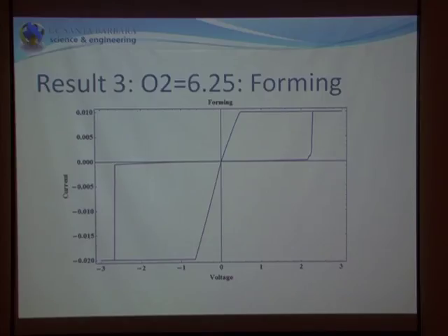And so I can tell you from Van der Pauw measurements that the film resistivity of this particular film is about half an ohm meter. So when I set out to do this experiment, you have 15 or 20 orders of magnitude between titanium and TiO2 in terms of resistivity, and I had no idea in which regime you'd actually be able to locate something measurable. And so 0 to 10 ohm meter you can actually measure in a conventional Van der Pauw configuration.